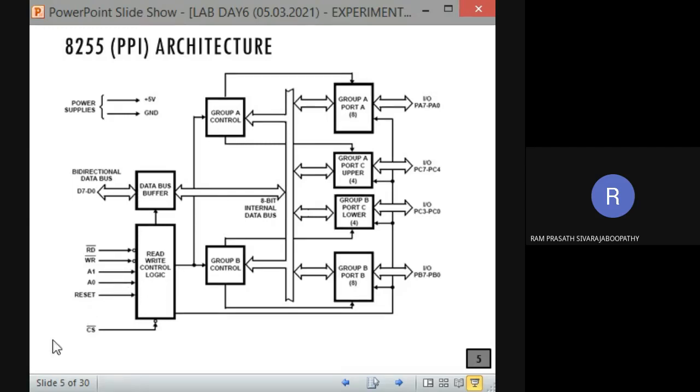The other 6 pins are given to some circuit logic, which is going to generate a low logic for that particular address combination. For any other combination of those 6 bits, it must produce a one logic. So that whenever that particular 8-bit address is used, this 8255 will get enabled. Is it clear now?